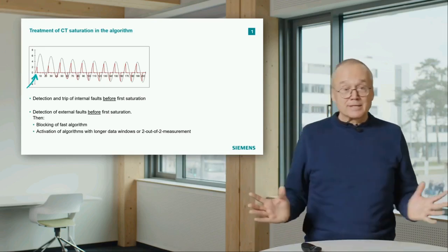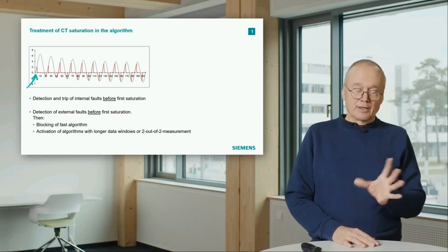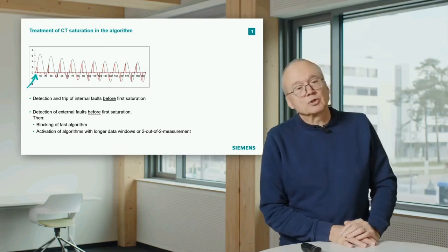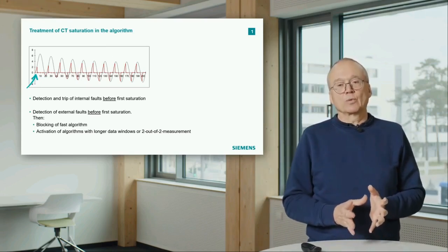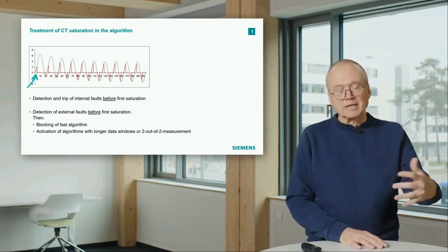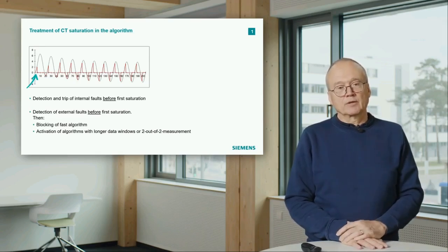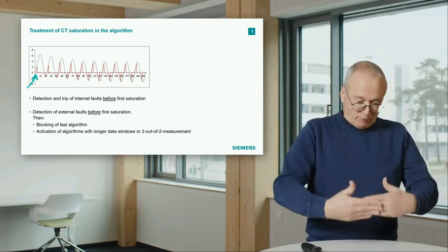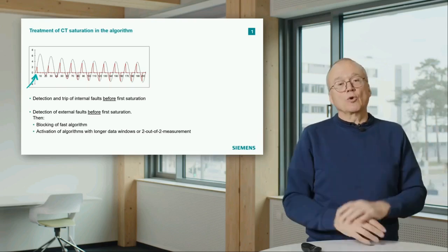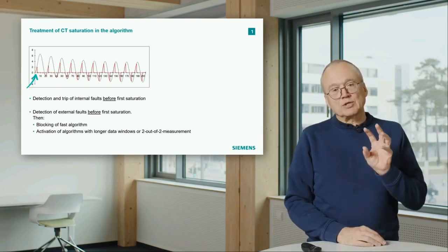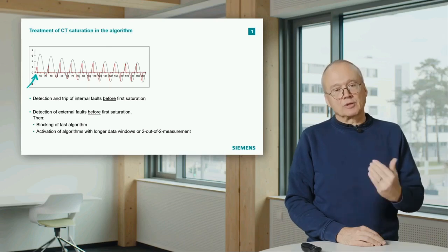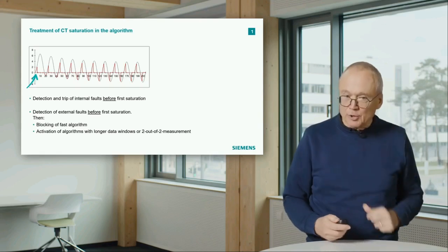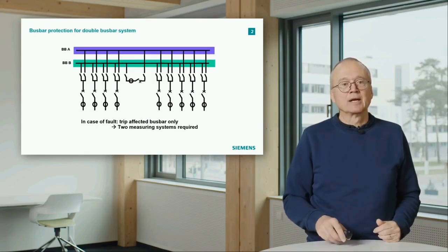You see, there is some challenge in the algorithms there, especially because normally the requirement for busbar protection is it should be very fast. We are talking here really about milliseconds. For the reaction time, of course, you have to add to that before you have the tripping time, the breakers have to open and so on. But busbar protection is the type of protection with really the highest requirements concerning tripping time. That were the challenges concerning the algorithm.